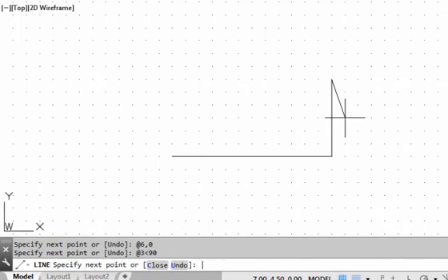One advantage of using a CAD system is that we can create and delete entities relatively fast. Unlike the traditional board drafting, no dirt mark will be left behind when we delete items in a CAD system. Next, we will create a horizontal line towards the left. We will use the direct input method for this line segment. Move the cursor directly towards the left side of the last point and Enter 2 to create the horizontal line.